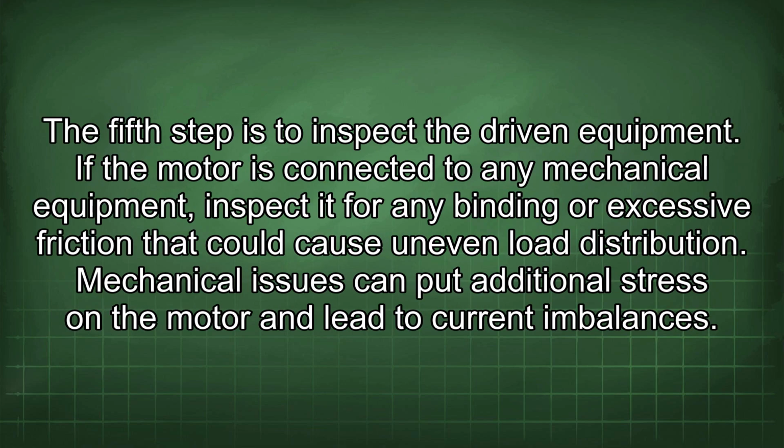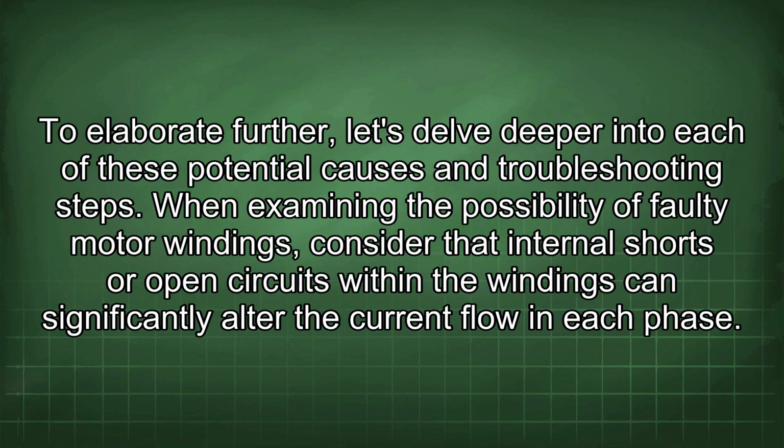The fifth step is to inspect the driven equipment. If the motor is connected to any mechanical equipment, inspect it for any binding or excessive friction that could cause uneven load distribution. Mechanical issues can put additional stress on the motor and lead to current imbalances. To elaborate further, let's delve deeper into each of these potential causes and troubleshooting steps.